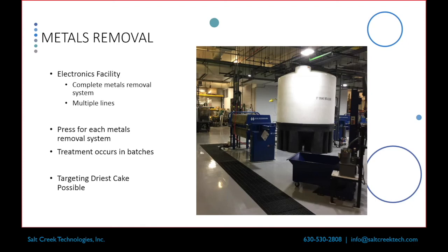And so what we ended up going with was a filter press, because in this case, I think it was 5 filter presses that are going to handle the sludge at a much lower cost than if you're going to do 5 belt presses or 5 centrifuges or 5 something else. And you're getting a really dry cake, so that high metals waste, which is usually pretty hard to haul off, is a nice low volume, low weight cake that you're generating.